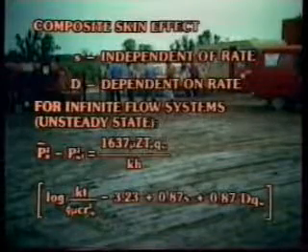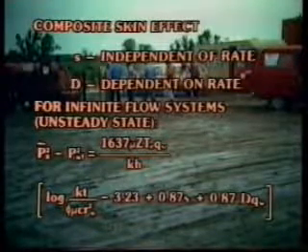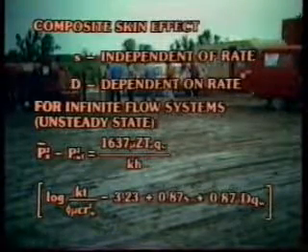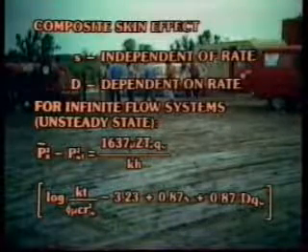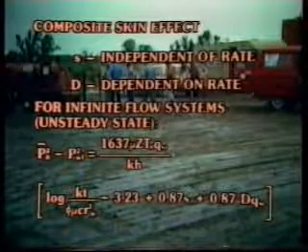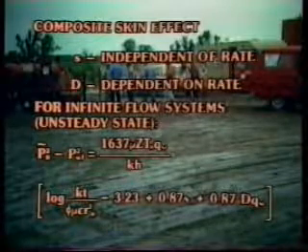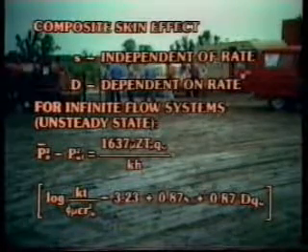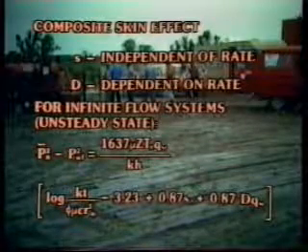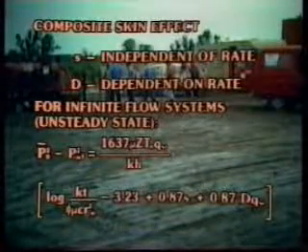If we incorporate the composite effect of skin, that is, the skin factor that is not rate dependent, S, and that which is, D, into our basic radial flow equation, we obtain what appears here. It should be pointed out that S is itself the composite effect of limited entry to flow and formation damage or improvement near the wellbore. You must discriminate between these two effects before knowing whether a stimulation job will be helpful. Details appear in your manual.